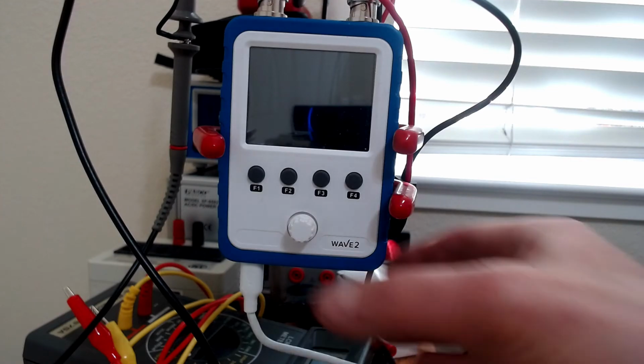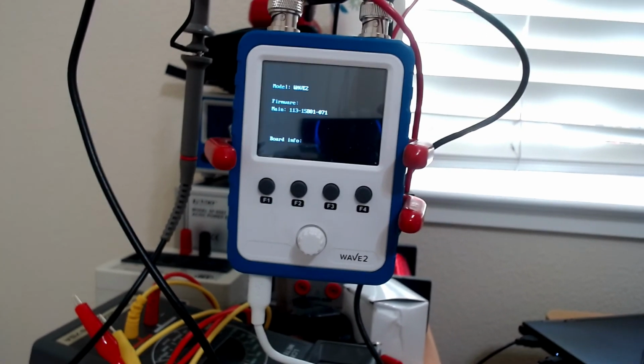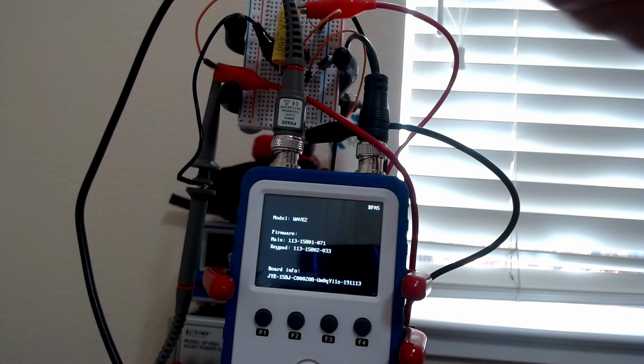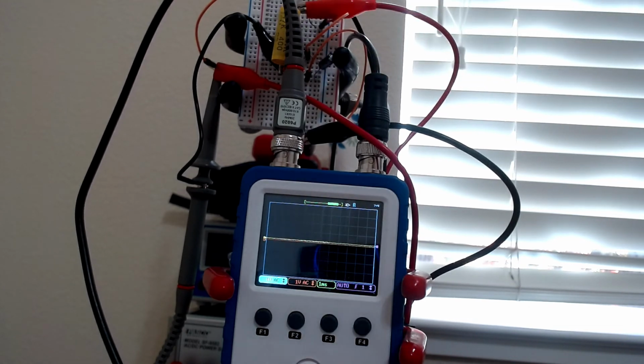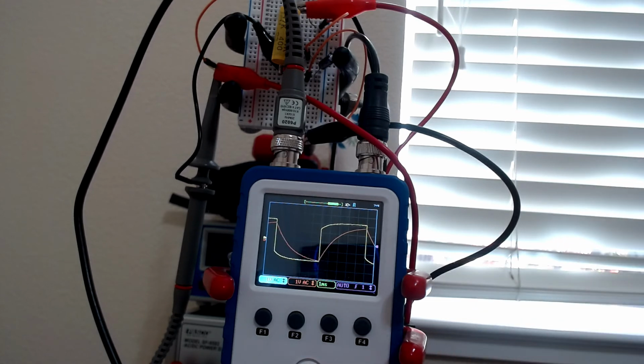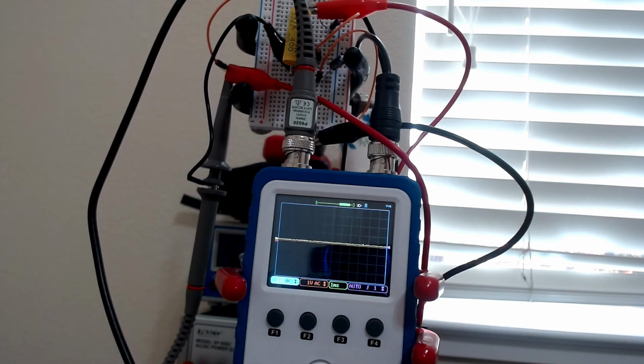Okay, so I have hooked up an RC circuit. The RC circuit's back here. This is the capacitor. There's actually 2 capacitors I put in parallel because I'm going to take one out so you can see the effect. I can't demonstrate the RC circuit with a multimeter because you just see a constant value. You cannot see the time dependence with a multimeter.